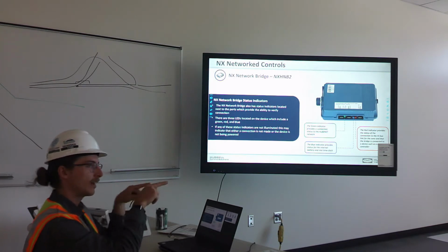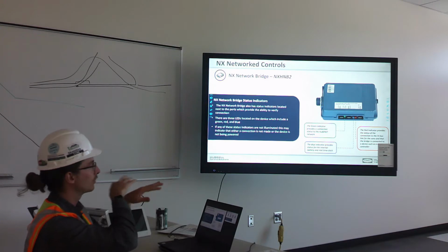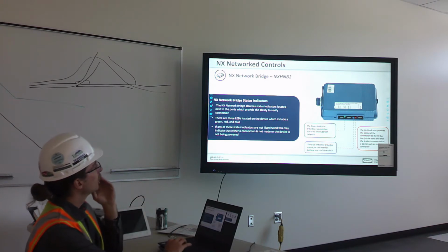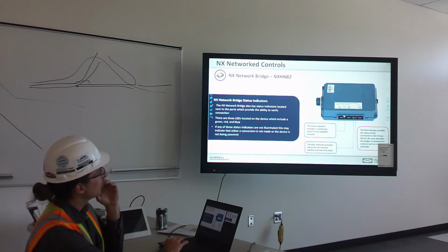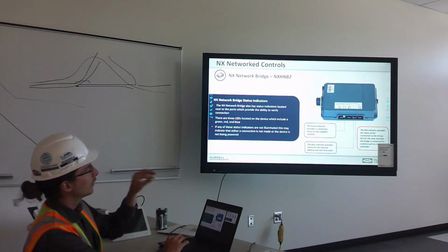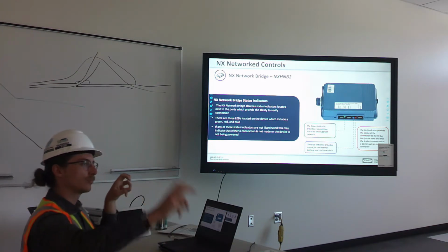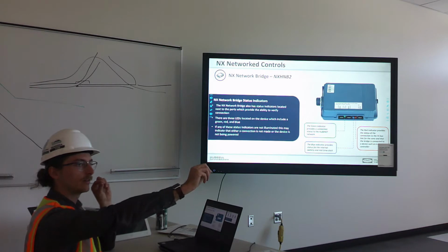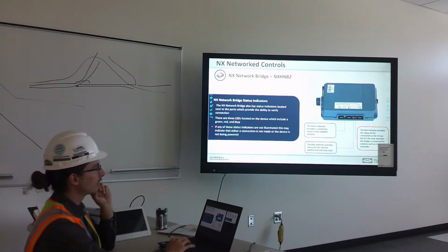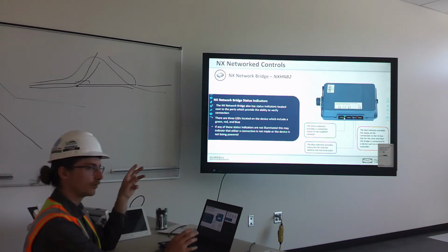They're both in and out, so it doesn't matter which one you use for going through the daisy chain. They've got a green LED on here, and that lights up when the bridge is talking to the next bridge down, on the end of that wire. So that's a really useful thing for troubleshooting the network.